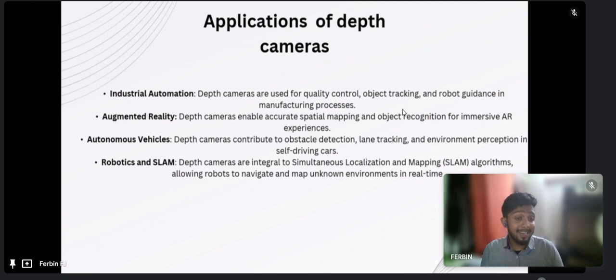But there is a disadvantage of 2D lidar: the lack of depth information. Yes, you get a good understanding about where every object is placed using a 2D lidar. But using a 3D depth camera, in addition to the two-dimensional information, we get a depth value. That is, it replicates the vision of a human eye. So you can have a better understanding of the environment or place where you work, and using that information, the navigation of robots or any autonomous systems can be done with ease.